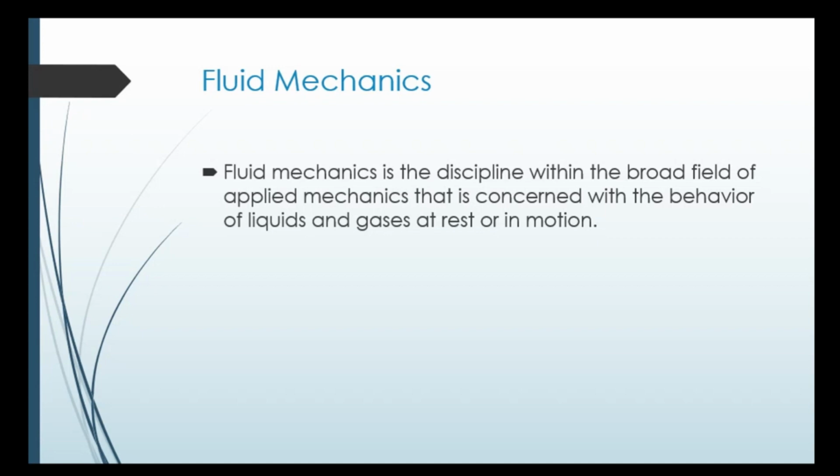The velocity of the top layer of the fluid will be equal to the velocity of the... No, it will stick to the body that is being used to apply force. So the top surface of the fluid layer will attach with the body, and it will bear the velocity of that body or that tool. So this is called the no slip condition.